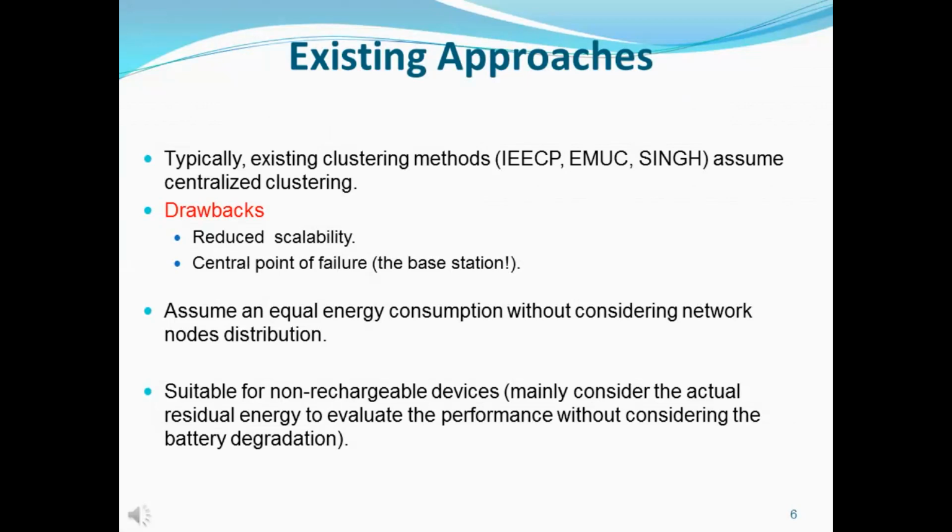Also, the existing approaches assume an equal energy consumption without considering the network node distribution. And also, the existing approaches are suitable for non-rechargeable batteries. They mainly consider the actual residual energy to evaluate the performance of their approaches without considering the battery degradation.